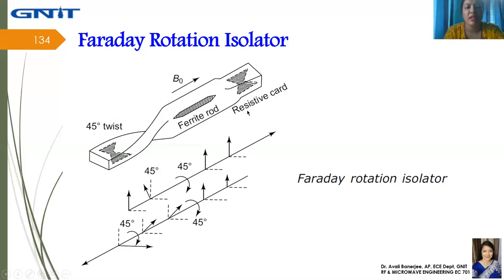The permeability depends upon the direction of field rotation and exhibits changes in the phase velocities. This results in a change in the plane of polarization of the main mode, that is TE11, which will experience gradual rotation theta during propagation to the other end.